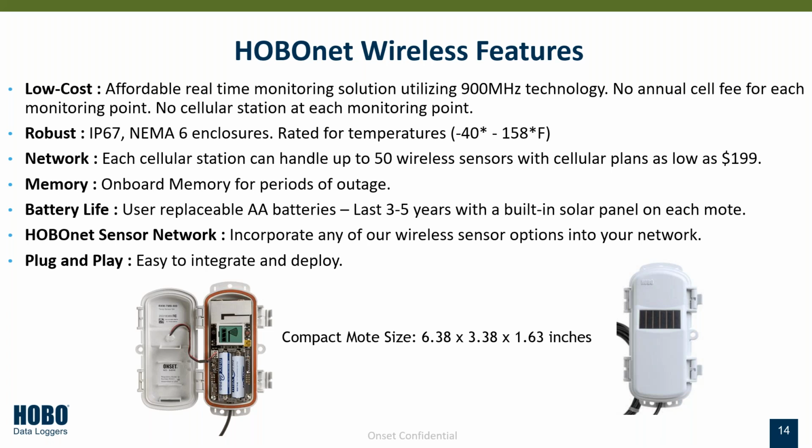It's definitely low cost. It utilizes that 900 megahertz technology. You don't have to pay the cell fee for each individual unit. There are NEMA enclosures as well. These are rugged enclosures. You're able to connect 50 of these sensors up. If for some reason one of these sensors goes down and doesn't find its way back to the main hub, it continues to log to onboard memory on the data logger itself.